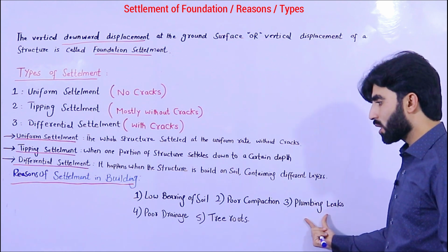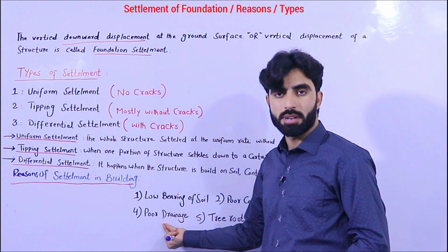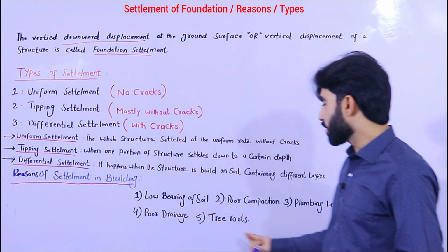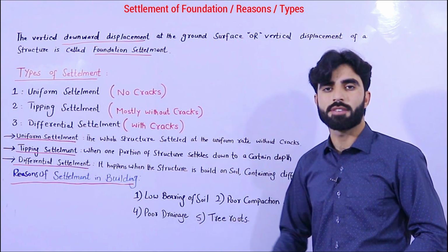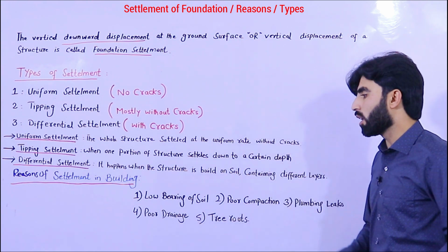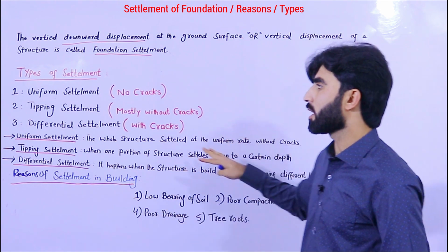Plumbing leaks, so control this. Poor drainage, do something for the drainage system, build a proper drainage system, and cut the trees or the roots inside the foundation. Therefore you will avoid these things, okay. You will not see settlement inside the foundation.